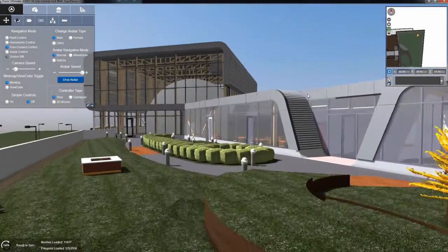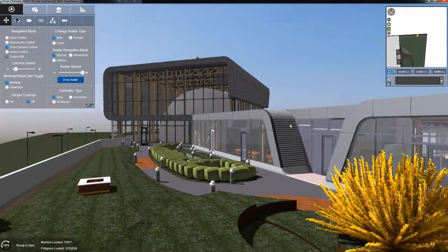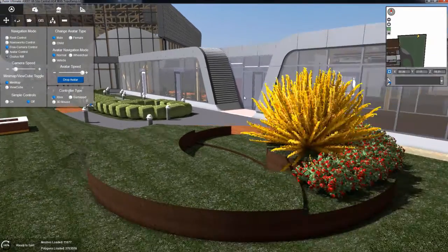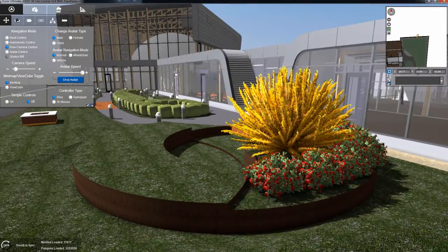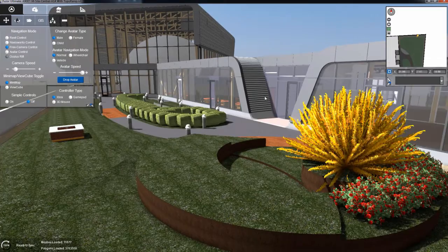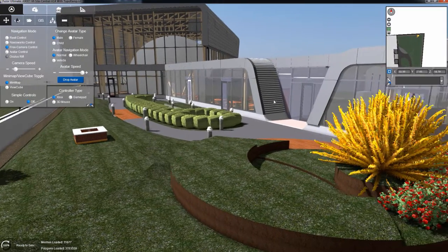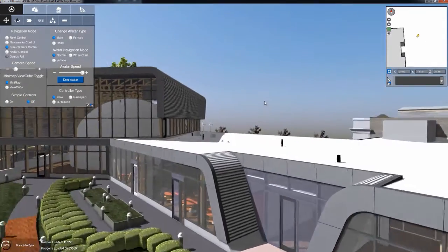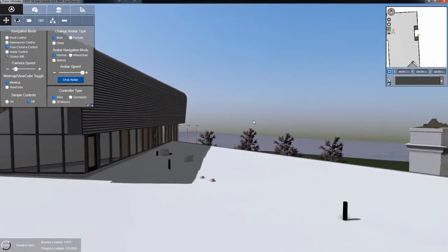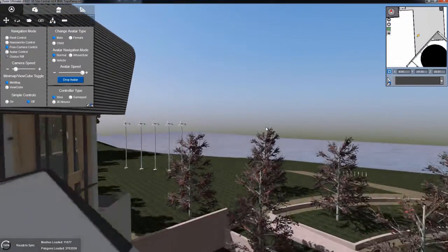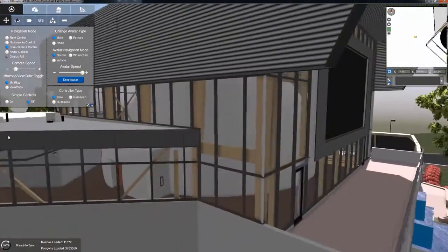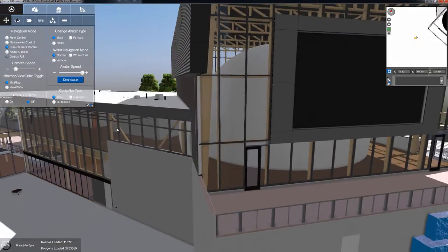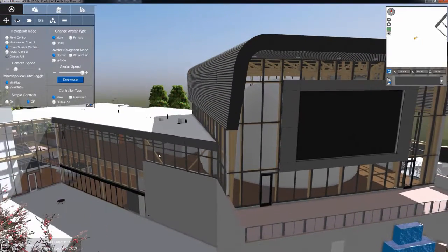Okay, so I've done my site walkthrough. I've checked for any blaring errors, made annotations of them. I've also checked the feasibility of some of my design options, and asked any of the appropriate questions. And I've saved out those annotations to deliver them to the appropriate parties. So, next stop on my hit list is I'm going to do a clash detection. And a good rule of thumb: always start your clash detection by checking against structural.